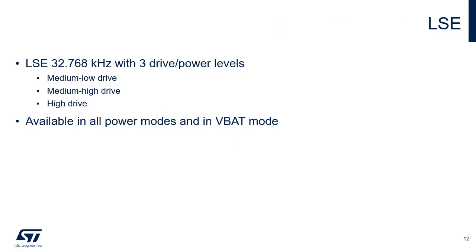The LSE clock is generated from a 32.768 kHz crystal or ceramic resonator. It has the advantage to provide a low-power, highly accurate clock source to the real-time clock, or RTC, for clock and calendar or other timing functions.